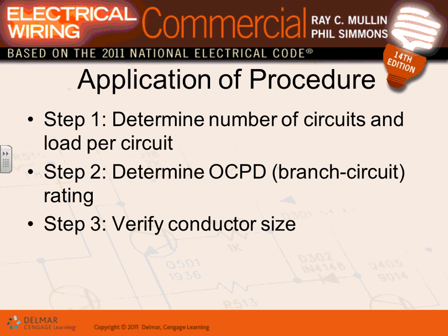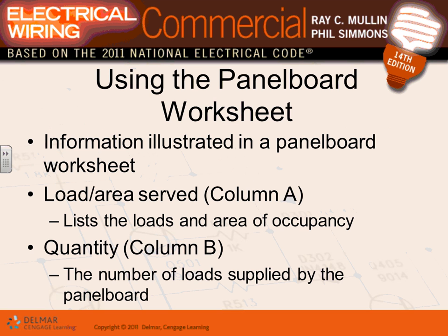Determine branch circuit, verify conductor. So this is how you do it. Determine the number of circuits and load per circuit, the overcurrent device, and verify the conductor size. And I'll go over an example, guys, that explains all this.